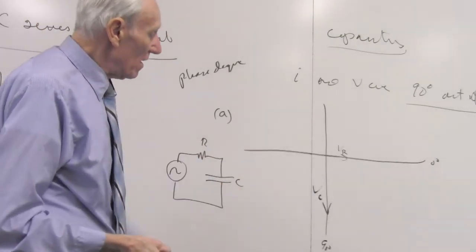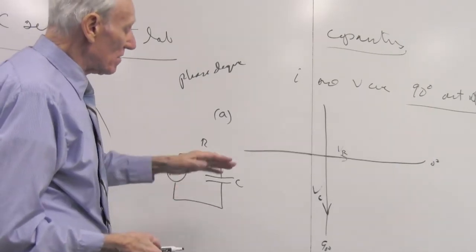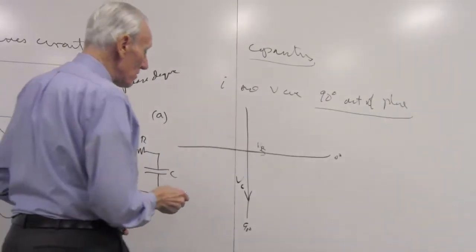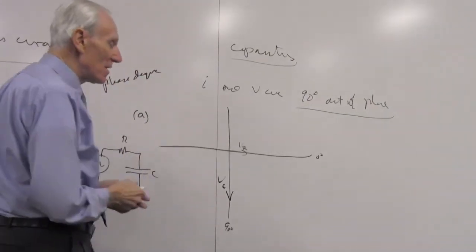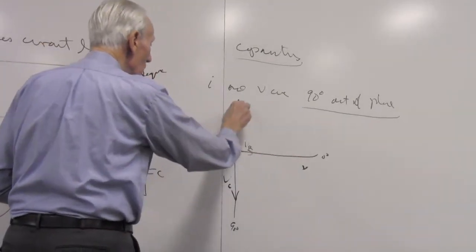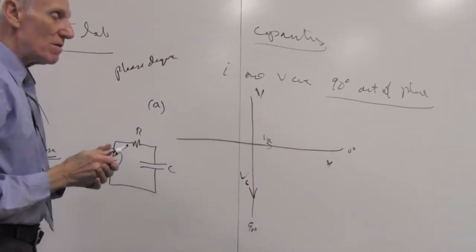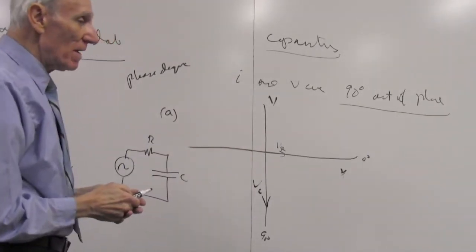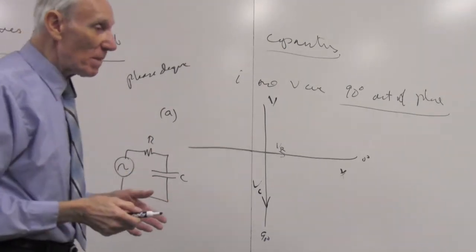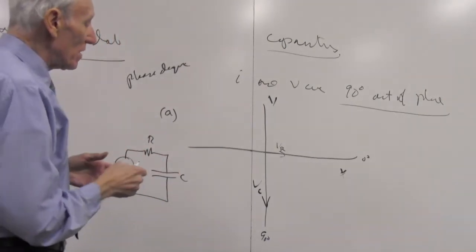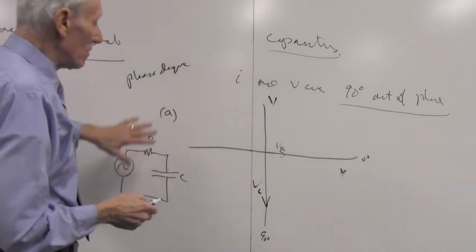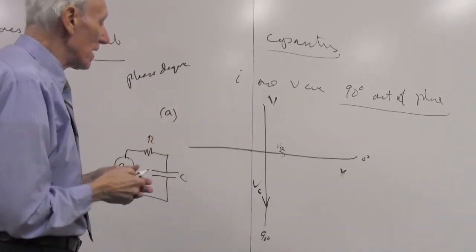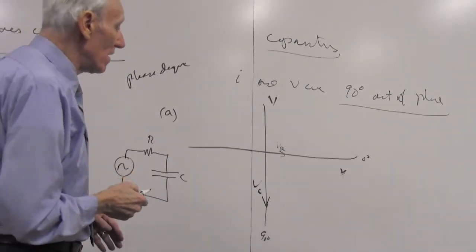And the theory says the phase relationship is 90 degrees between the current through the resistor and the current through the capacitor. So because that's 90 degrees, we have a nice x, y coordinate system here, and we can use the same mathematics as we use for vectors, which have x and y components. Voltage is not a vector, but voltage can be considered to be what's called a phasor in these more complicated circuits, where the voltage and the current have shifts in phase because of what they experience in the circuit.